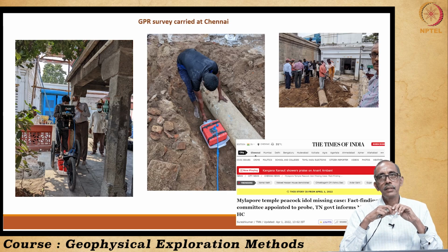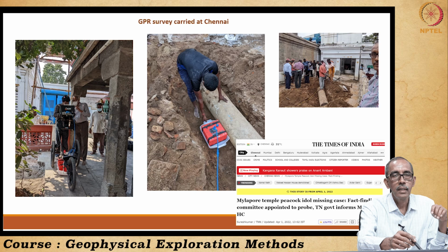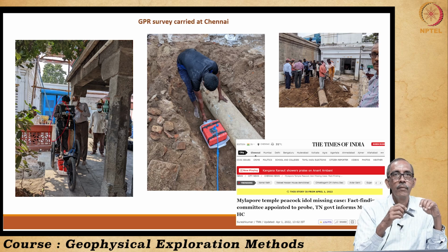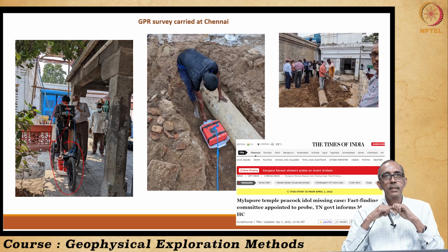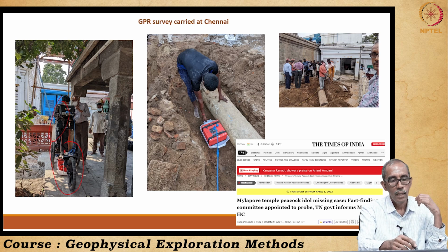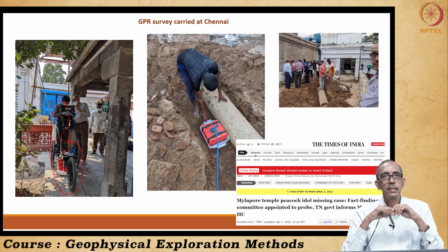And in another study, we had deployed ground penetrating radar along with my colleague Dr. Lenin Kalyanasundaram from Anna University. We are using a radar system which is mounted on a tricycle with the antenna at the bottom as well as receiver just adjacent to that, which is transmitting the signal into the ground, and as we push this tricycle, we are able to continuously study a particular cross section.